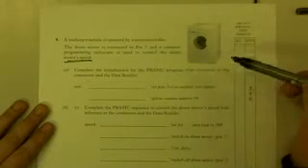Okay, got another programmable control question here, this time a washing machine. It says the drum is connected to pin 7 and a common programming technique is used to control the drum speed's motor. So it looks like we're on the speed control of a DC motor. Complete the initialization for the PBasic program with reference to the comments and the data booklet.